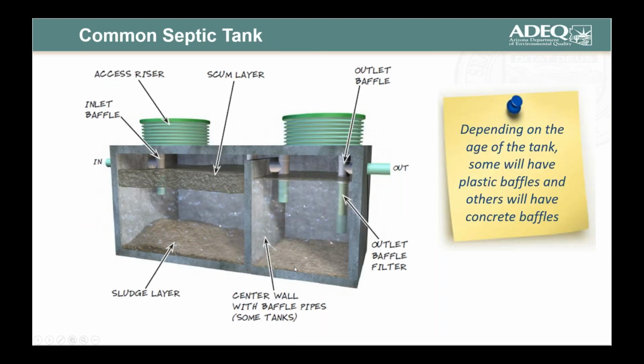Now, let's just look at your common septic tank. It does not exactly represent Arizona's version of a septic tank, and I'll point out the minor differences. First of all, we see we've got the inlet over here, and we have the outlet here. The outlet invert is lower, needless to say, than the inlet. I have gone to places where they've reversed them, and you can't do that in the field without bad consequences.